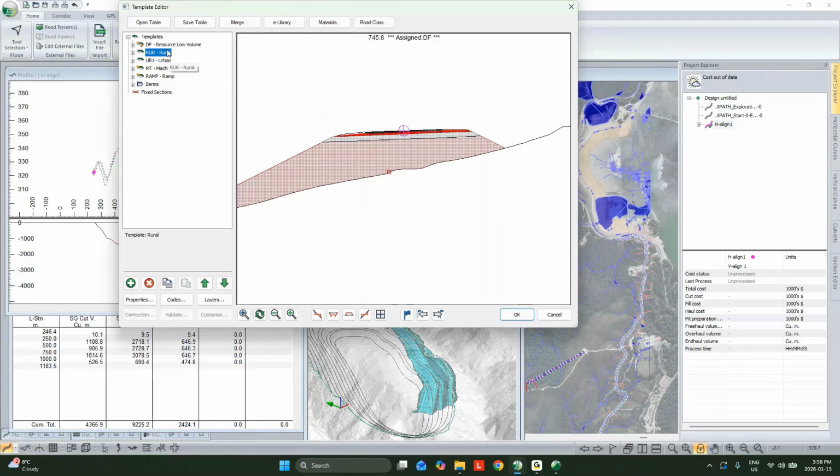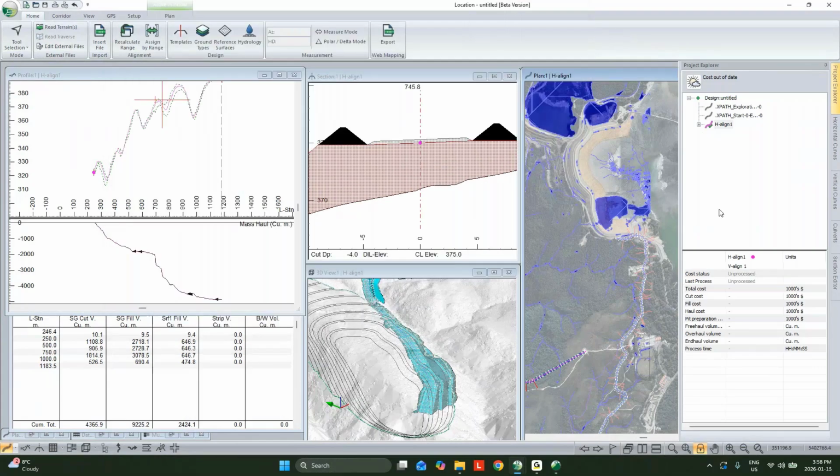So we could just basically set up our cross-section geometry to be appropriate, and we could choose that location as we'd like. And in that case, with an earthen dam, again, kind of like the ramp, your goal isn't really to minimize earthworks, it's to put the dam where you'd like to put the dam and know the earthworks involved. So tailings dam, yeah, I would use that manual workflow and click it in where you'd like. With that, you'll also see a cross-section template component specific for earthen dams with a different material for the core available later in 12.2.